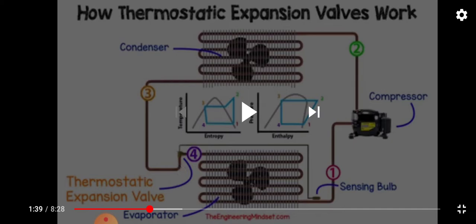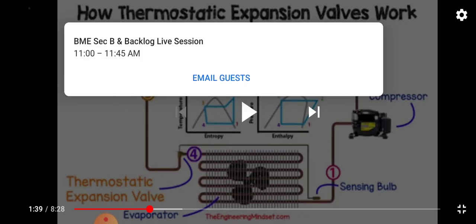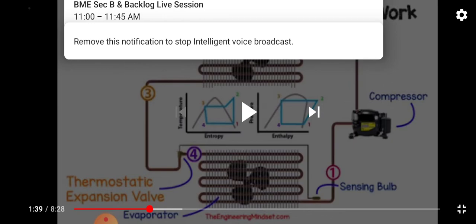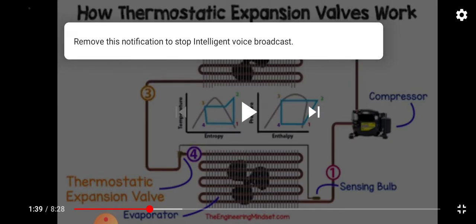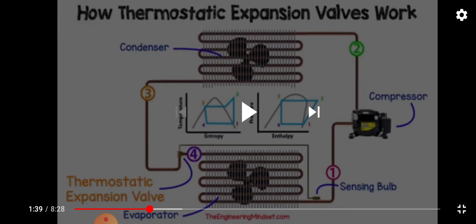You can see the capillary tube, but if you go towards a higher chiller, like a big floor standing unit, you will see the expansion valve. The working principle is all the same, but the thermostatic expansion valve is advanced. It can control the flow volume with reference to the temperature of the condenser.